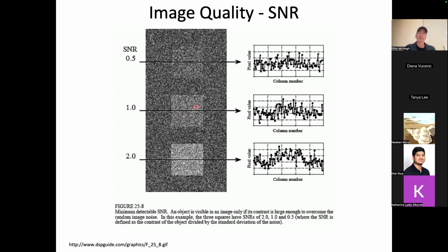And then I look at this sigma value inside there, divide that, I get 1, okay? So the step up in contrast is 1 noise unit or 1 sigma value. If I look at the profile through that, you can see it's got a higher mean across here and then back down, but it's not that obvious that there is a signal there at all, right? But that's what signal to noise of 1 looks like.